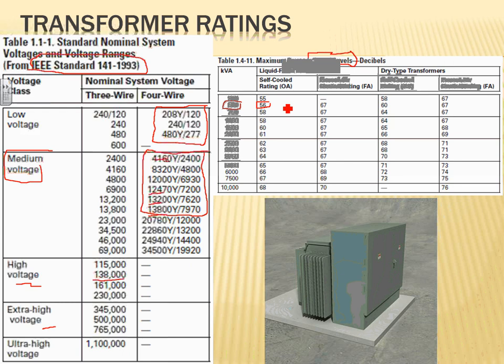So if anybody asks you about the noise level of this transformer, another thing I was asked in the past was the noise level and losses of a transformer. Your fellow mechanical engineers will ask you, what are the losses of this transformer, the heat generated, so we can calculate our heat. All these transformers also have losses, 99% of which is heat, so they can calculate their heat gain for the building. So just be aware of that one.